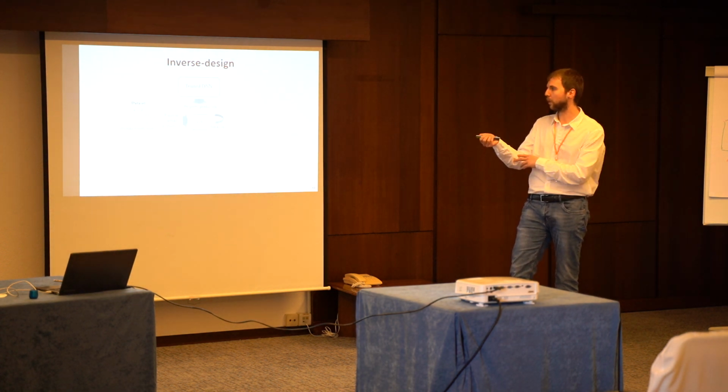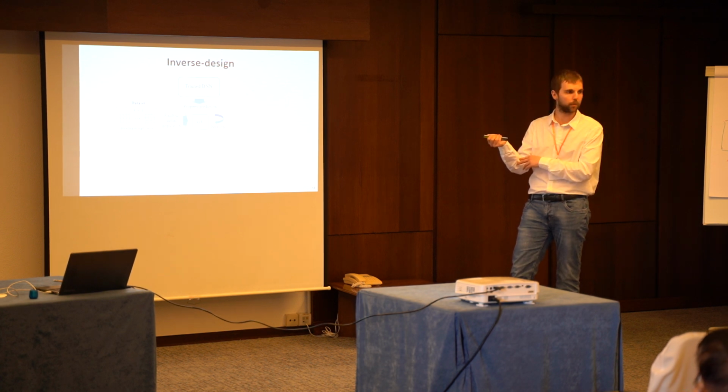The first step is to find the inverse design, so finding optimal architectures. We have our dataset composed of architectures with the corresponding buckling strength vector for different loading directions. Then we start with a random initial population and use a genetic algorithm. We don't have time here for the details, but it is an optimization algorithm which provides you some new design candidates, new architectures, whose property, which is the buckling strength in this case, but it might also be, for example, fracture toughness or whatever you want, I can predict with the previously trained deep neural network.